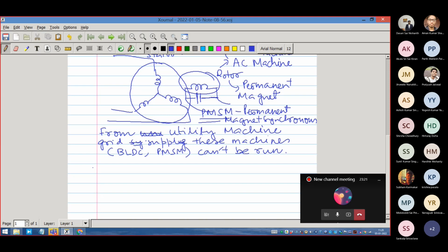It is a brilliant construction. It doesn't have any rotor terminals. The rotor terminals are short circuited, and short circuited means we get scared that, oh, short circuit means a lot of current will go. The brilliance is in that they understood that the current will not be high because the machine operates with such a principle that the induced voltage in the coil itself is low.